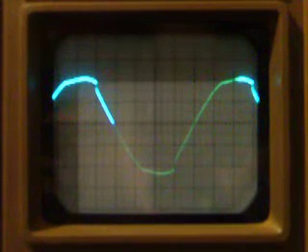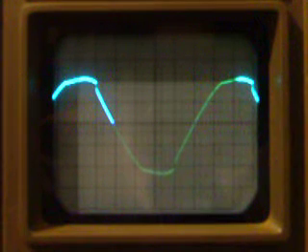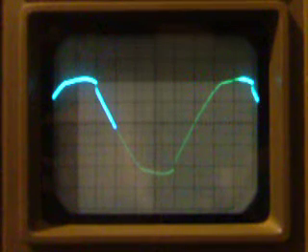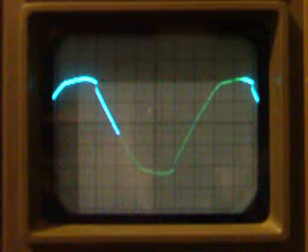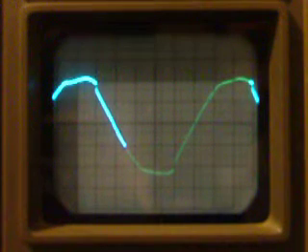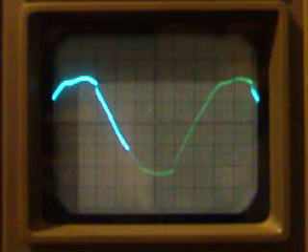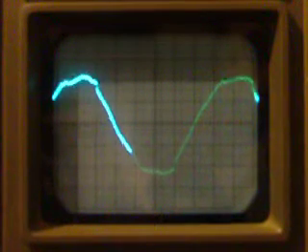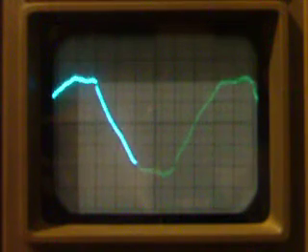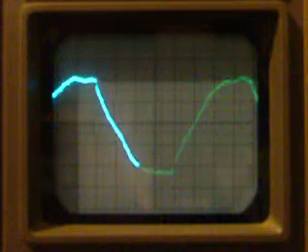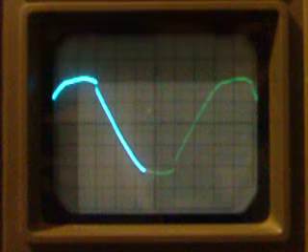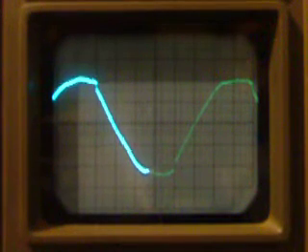Now the real interesting part comes when I put a signal, a sine wave input, into the amp. I'm going to start with 400 Hertz and slowly bring up the master volume. And what we're going to see is how the input signal is modulating the heater winding output. And back off the master volume, and that modulation goes away. And bring it back.